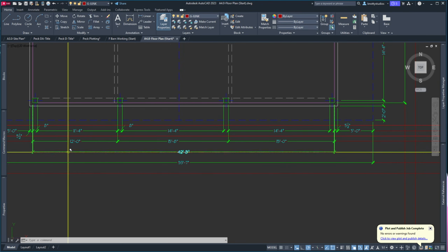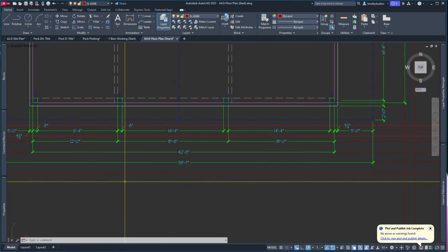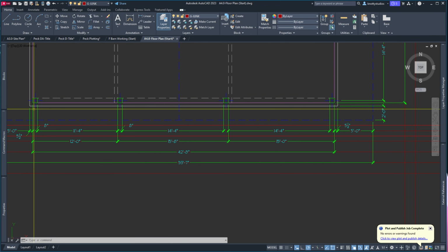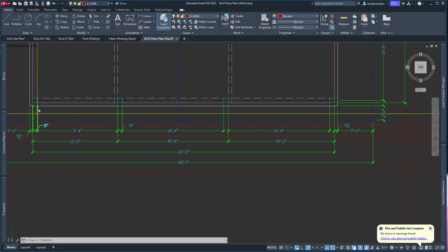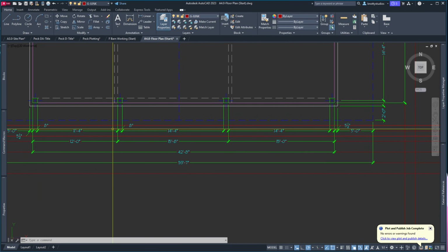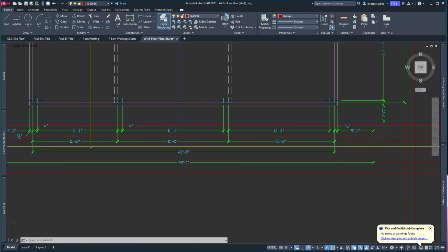If it was a 44 out to out structure, which is what we want. So here I'm short. So he wants from center here out to the edge to be 14. So that would be about 13 feet because I've got 8 and 4, so 12 inches. So this needs to be 13 feet.